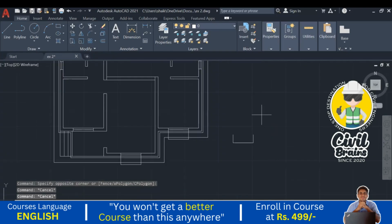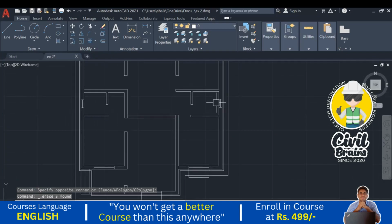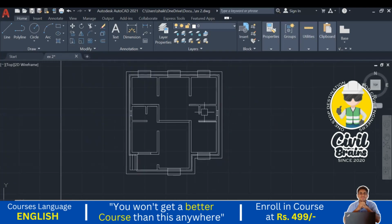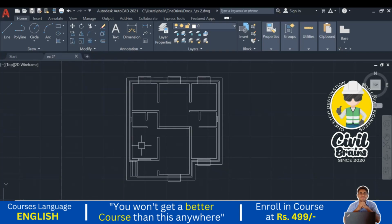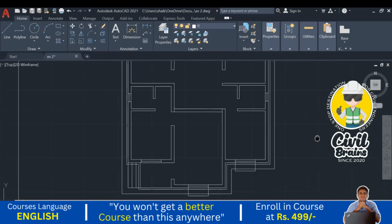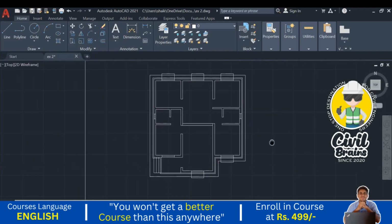Okay, and for ventilators we are not providing the chajja. Sometimes it is provided, but sometimes it is not. Why is it not provided? Because the size is very small and the depth is also very small. That's why we are not providing it. So we have provided the plinth here, we have provided the chajja plinth projection, we have provided the slab projection, and we have provided the chajja projection. Correct? So these things we have provided.